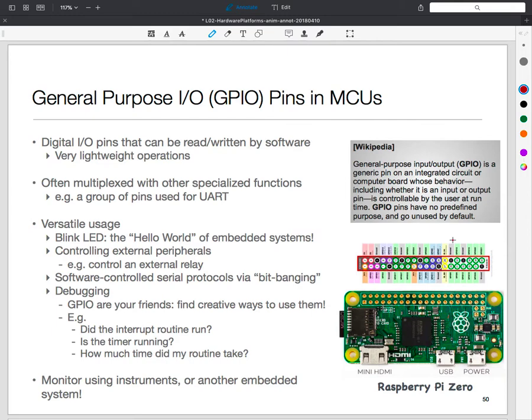Usually with these GPIOs, you can hook up an LED to it along with a resistor, or perhaps even without a resistor. So the LED is rightly matched, and then you're good to go. Very easily done. Usually these pins are designed to provide sufficient current that you can do meaningful stuff with it, but not a whole lot of current.